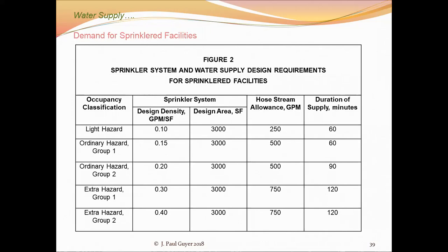And you will notice that the design area of fire is still 3,000 square feet. And this may seem a little counterintuitive, that the design area of the fire remains the same from light hazard through to the most hazardous occupancies. It's still 3,000 square feet.